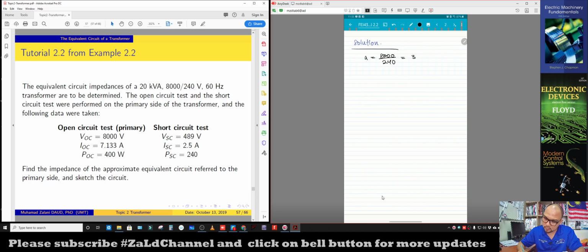So we get the turns ratio of 33.333. This turns ratio has no unit. And then what we do is find the power factor, because we want to determine theta, the angle of the impedances.